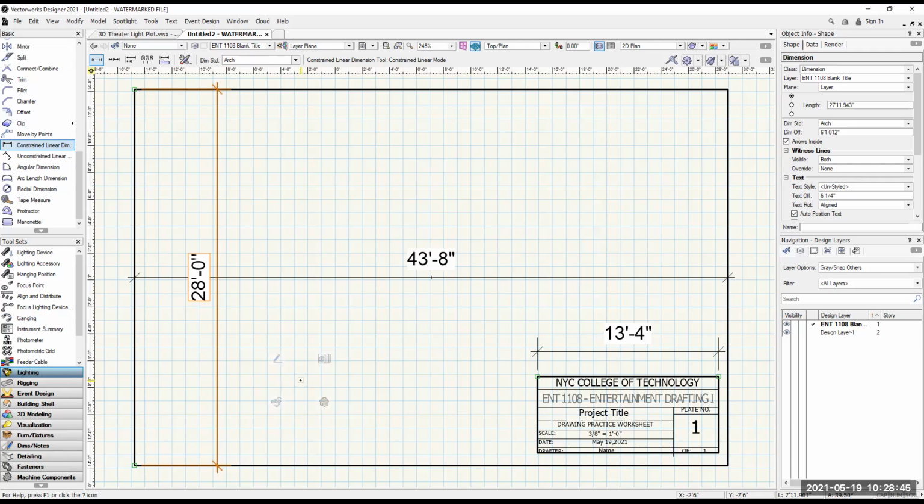I have to figure out what I did with my calculator. There it is. So it's basically what I want divided by what I have. 28 feet times 12 is 336 inches. So if I want to take it down to 11, it's 11 divided by 336. So my scale factor is 0.0327. That's where you would put your scale. See down here, you would be trying to scale it to that.